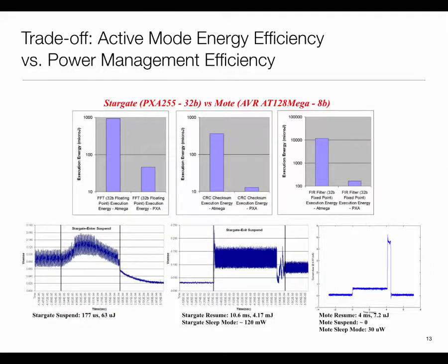So last time around, we were looking at how there's a variety of processors, and the main thing we often face in embedded systems is a choice between things which are more powerful and more efficient in terms of processing in bulk, but on the other hand are very inefficient in terms of power management, in the sense that they consume a lot of power when they are asleep, as in they're still powered up but not doing anything, or are in one of the sleep modes that the processor provides.